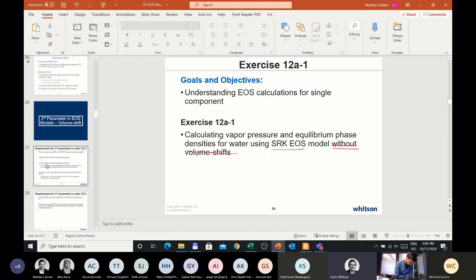There are kind of two approaches to dealing with that. The one is to use a more sophisticated, like a BWR type equation of state to get the compressibilities right, and then generate the black oil tables with that equation of state. But there's almost nobody using BWR type equations of state for these petroleum mixtures.